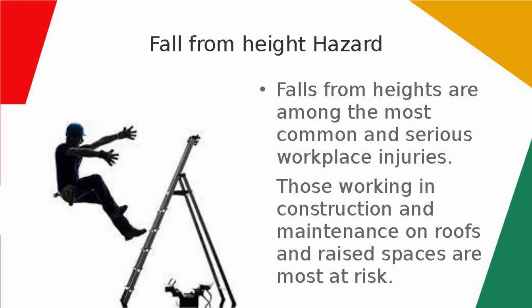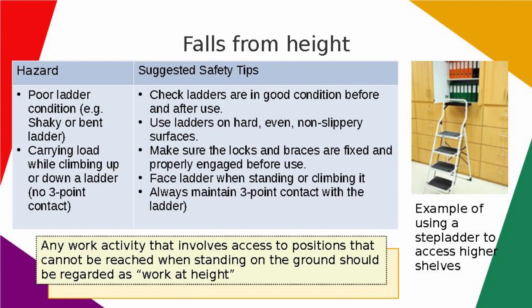Fall from height hazard. Falls from heights are among the most common and serious workplace injuries. Those working in construction and maintenance on roofs and raised spaces are most at risk. Falls from height. Hazard. Poor ladder condition, for example shaky or bent ladder. Carrying load while climbing up or down a ladder, no three-point contact.